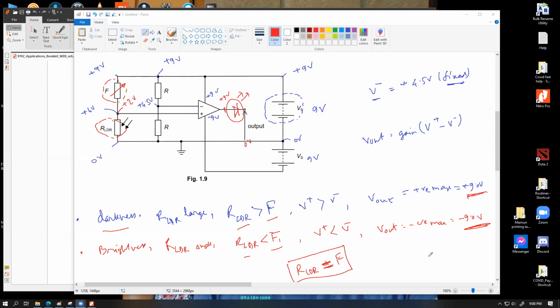So in many cases, we use a bimetallic strip. For example, all the water heaters that you come across which have an automatic switch off. You plug it into the electrical socket and press the switch, and when the water starts boiling, it simply goes off. All of those water heaters still work with a bimetallic strip because it is reliable, and you have enough heat available, because it's a heater by design for the bimetallic strip to work. And you don't have electronics involved in most of these things because we do not have to control the temperature of boiling water electronically.